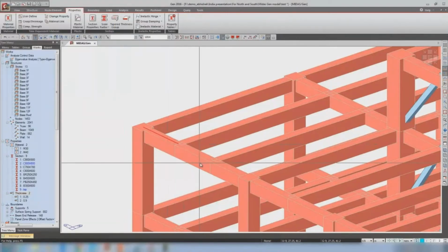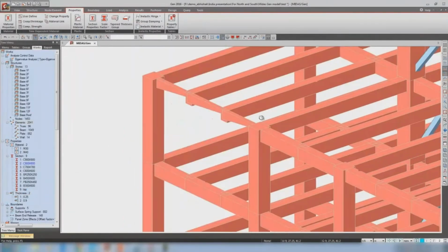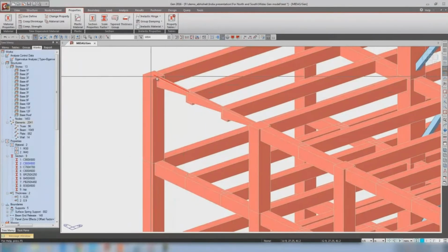Now I just select these three beams and just drag it to the screen, this tab, and just drag. Now you can see here, this is my one property, which is here 450 and here it is 200, but I want this as 450, but at the end 200, and the in-between dimension should be calculated linearly. So I just hide this one.